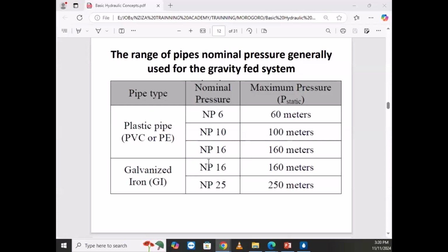For example, here it is showing you that the pressure is 180, and then we did not put a pipe for PN16. So in the model, it's very easy to locate and check if the pipes that you are putting match the pressure.